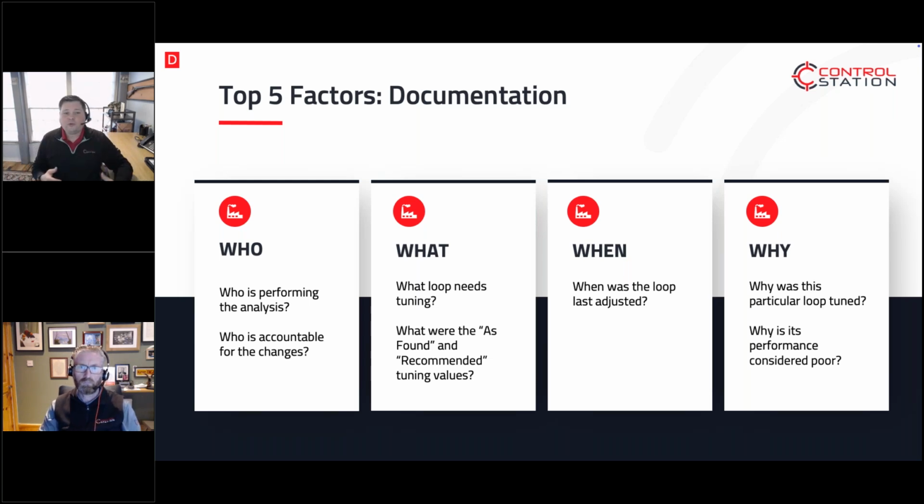I'm also a huge fan of historizing tuning parameters, right? No, I don't work for historian companies. I don't get a commission on the tags that you add to your system, but a history of all of those values is very, very critical, because there's nothing worse than coming in at 10 a.m. and hearing, oh, this loop just went crazy last night, right? And to have a history and go, well, yeah, because they changed the tunings at 2 in the morning. It was working fine before that. But if you don't have that history, you don't know, and you're left trying to diagnose a problem from the ground up, and it's wasting time, right?